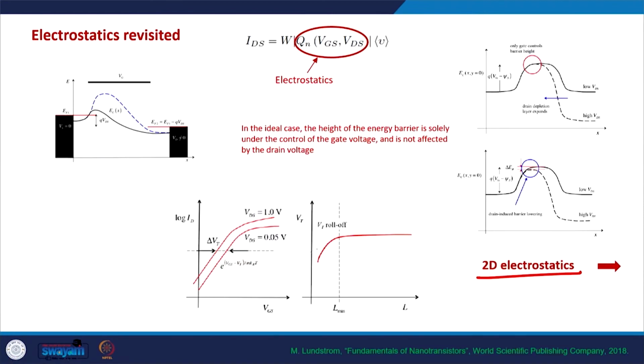So, we see that the threshold voltage rolls off, which means that the voltage at which the channel is getting formed, the channel is getting inverted, is getting smaller, and the IV curve, the transconductance curve ID versus VGS, is getting shifted to the left side, and this is prominently important around the threshold